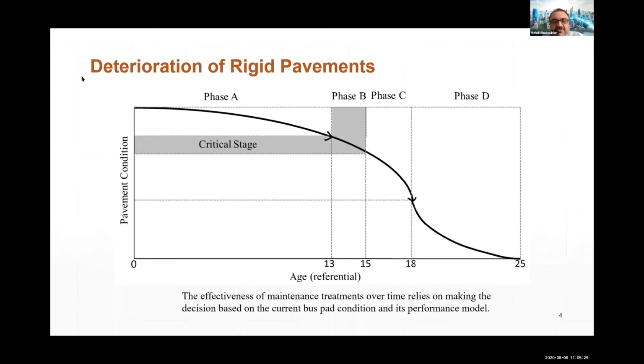This phase is relatively short. Once the surface damage is widespread, destruction is accelerated. At the start of this phase, reinforcing the pavement surface usually is sufficient, so maintenance is relatively low cost. So it's the best time to do the action in the maintenance plan, in phase B.